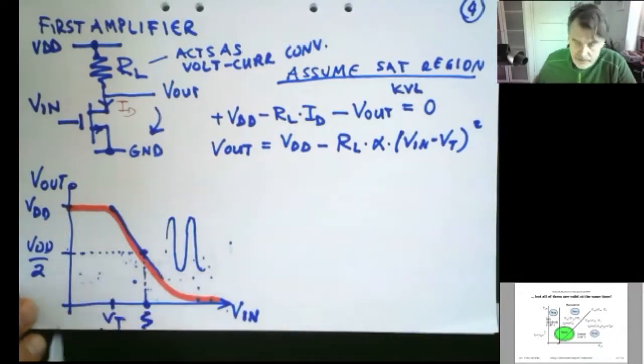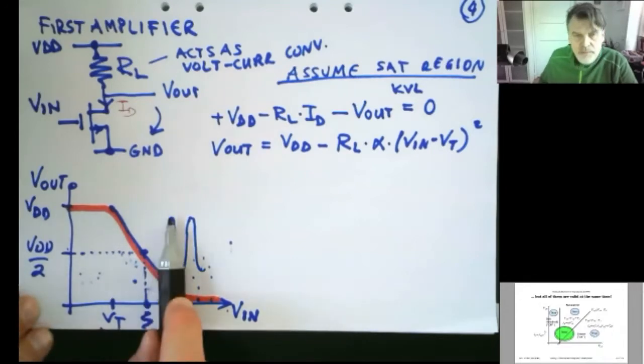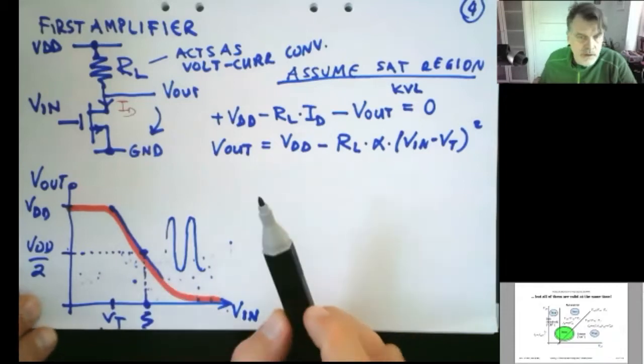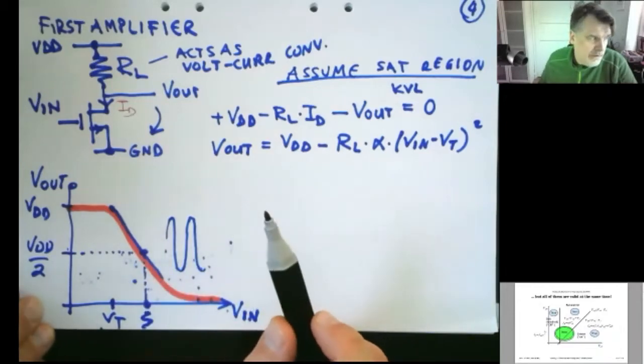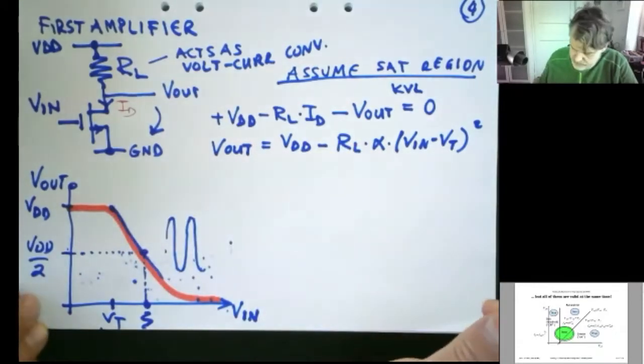Now, what you will find as an analog designer is that this point is actually not optimum from a gain point of view. It's optimum perhaps from a swing point of view, up and down, but it will not give you the highest gain. There are other requirements for that. So that's another type of trade-off that we can do.